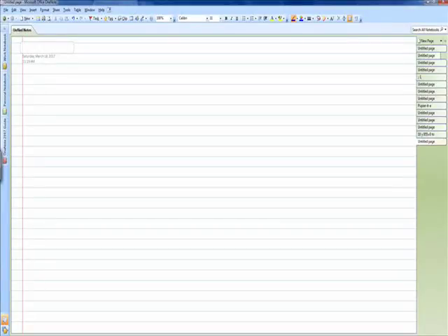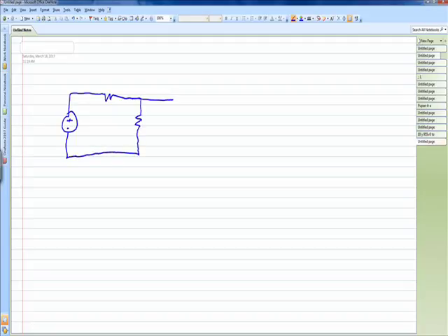In this tutorial we will learn how we can simulate a circuit in PSPICE using the classical coding based technique. So in order to do so, let's have an example here. We are going to simulate a circuit in which we will find the unknown voltage and the current for this very simple circuit. So we have a voltage source, one resistance here, and another path connected here. I think this circuit is enough to understand the basic concept.